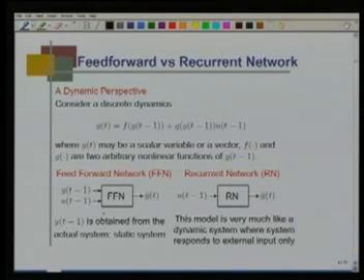In a feed forward network, if I model this dynamic, how do I do it? So I have a feed forward network. This feed forward network can be a backpropagation network, a radial basis function network, and the output is computed while inputs are the previous output of the system, actual output of the system, and the input to the system, that is ut minus 1, and this is system output, not the network output.